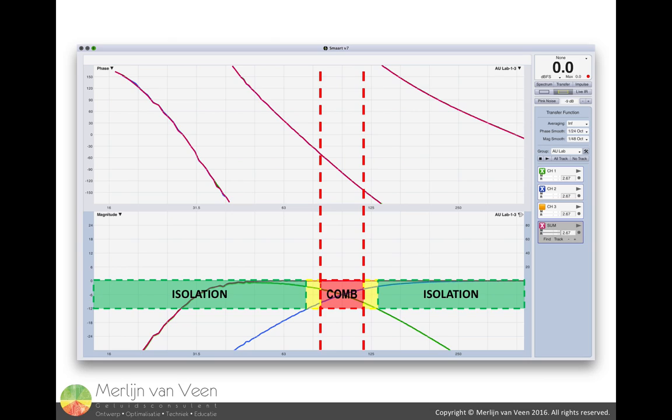However, in real life, it's very likely the delay locator won't be able to lock on to the subwoofer for several reasons besides the severely compromised data as a result of band limitation. As distance to the subwoofer increases, signal-to-noise ratio will become poorer, to say the least. This can be countered in two ways, by either increasing the number of averages and/or increasing the level of the subwoofers and improving signal-to-noise ratio with brute force.